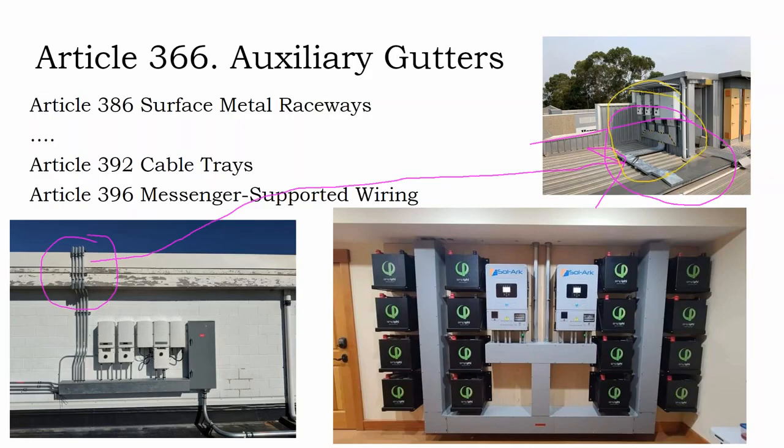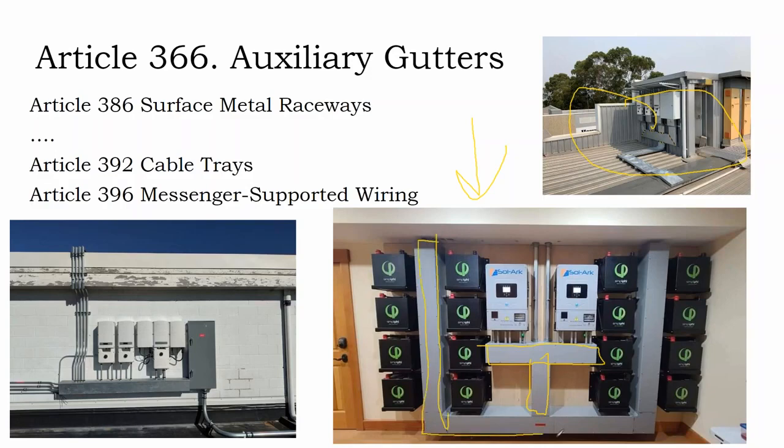You really only see cable tray on commercial systems because of its cost. Even by the foot, you're getting into, I'd say, $12 or more, and so that can get quite pricey for the conduit run. But what does it gain you? Why do we use it in commercial jobs? And even here in this, I'd say, high-end looking residential project, this is not my project, it's Ben McFeeder's on Facebook, he's using gutters as kind of a residential poor man's cable tray.